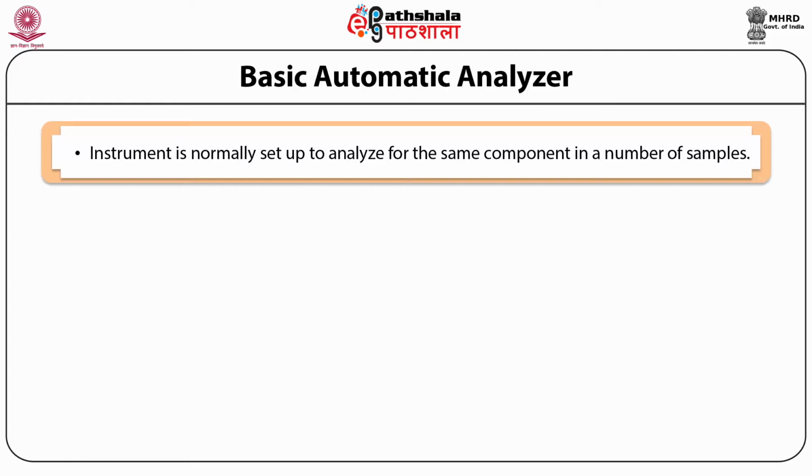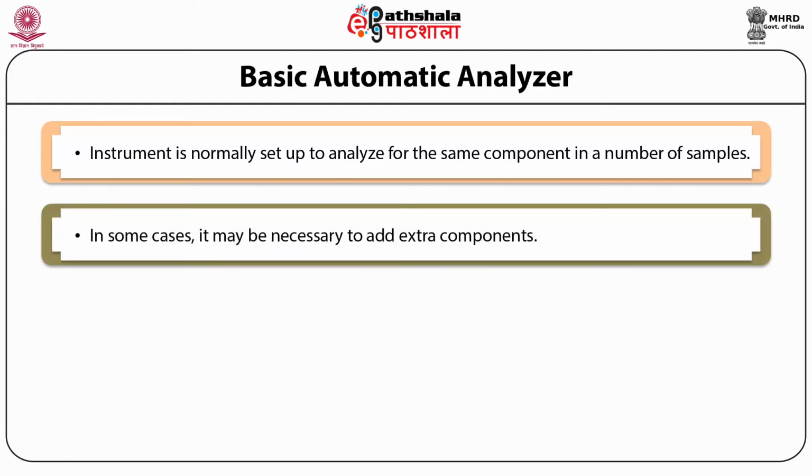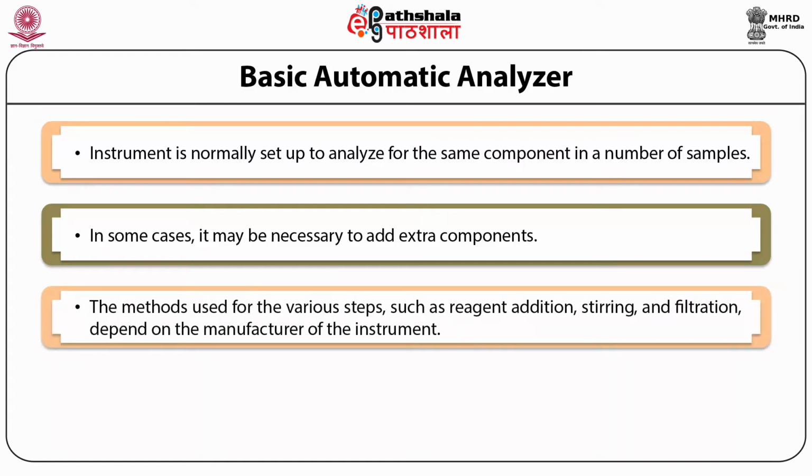and different components can be determined by the use of different reagents. In some cases, it may be necessary to add extra components, for example, to provide for the further addition of reagents after the filtration step. This is facilitated by constructing the instrument on a modular basis and at any time using only those modules required for the specific analysis. The methods used for various steps, such as reagent addition, stirring, and filtration, depend on the